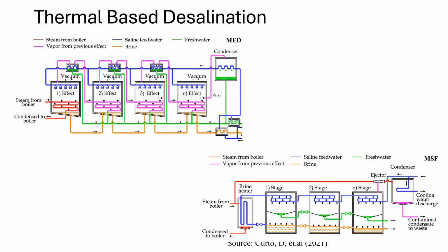These are schematics of these processes, and to put it simply, the multi-stage flash on the right-hand side at the bottom was introduced in the early 1950s. It is based on the principle of distillation through multi-stage chambers, where the pressure is suddenly reduced at each successive stage. And most conventional plants using this technology usually have from 10 to 30 stages at this time. And at every stage there is a decrease in temperature of around 2 degrees.